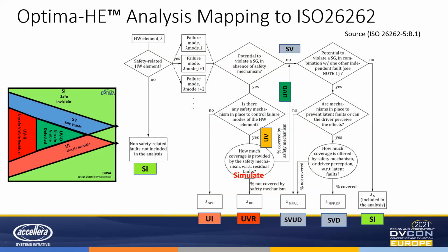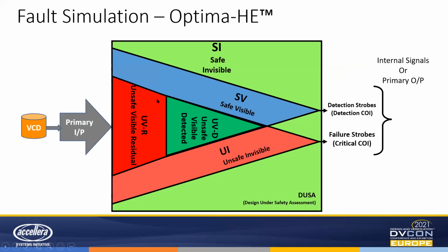But what I want to focus on now is that after analysis, you're going to get the UV faults as UV detected and UV undetected, which we call residual, right? So after this stage, you further classify the faults into detected and residual faults, which are also important classifications for your ISO 26262 recommendation or the FMEDA products.